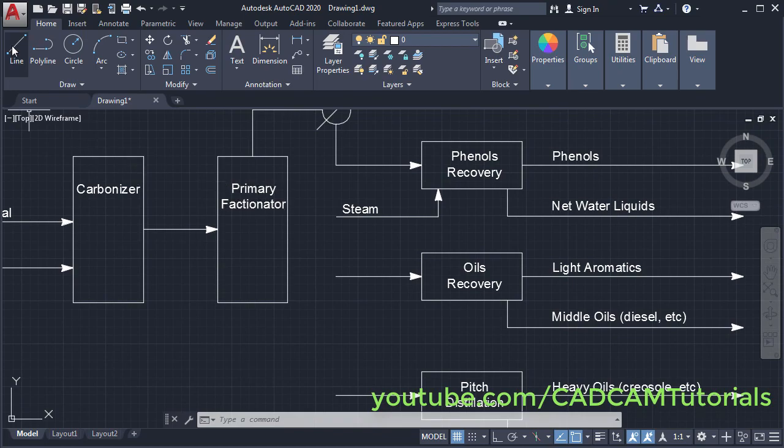Click on line. Click on this midpoint. Take your cursor on this side. Take it below. Drag this endpoint and click enter. Then click on this line. Click on this square blue box and click on this endpoint. Escape.